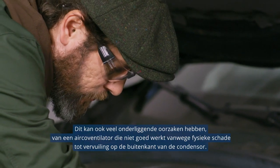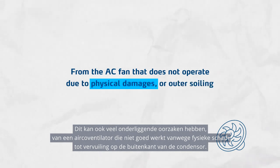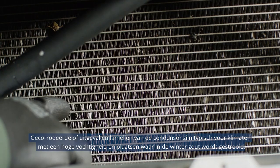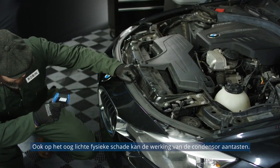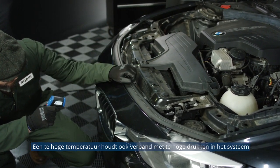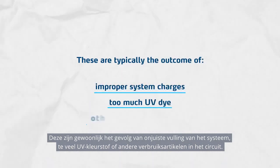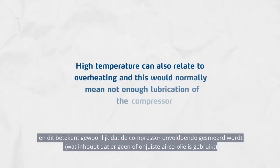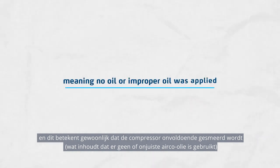This can also have many potential root causes, from the AC fan that does not operate due to physical damages, or outer soiling of the heat exchanger surface. Corroded and missing fins are typical for climates with a lot of moisture and where salt is spread during the winter. Seemingly light physical damages can reduce operation of the condenser. Too high of temperature is also related to too high of pressure in the system. These are typically an outcome of improper system charges, too much UV dye, or other consumables in the loop. High temperature can also relate to overheating, and this would normally mean not enough lubrication of the compressor, meaning there was no oil or improper oil was applied.